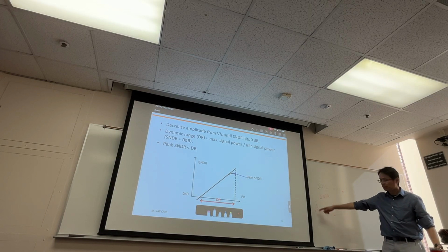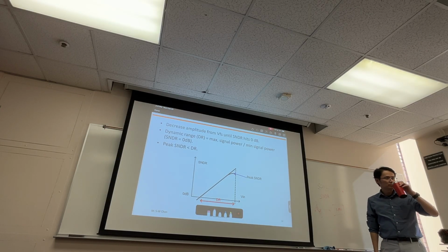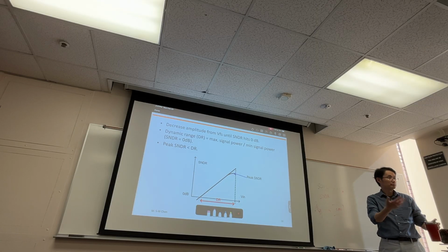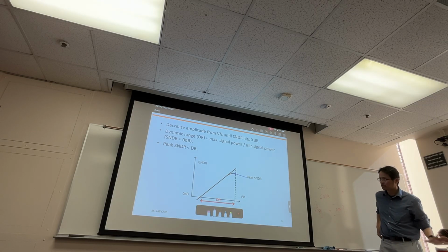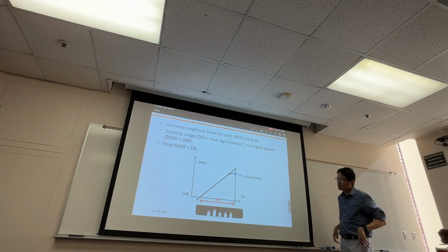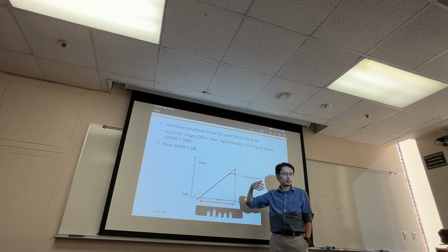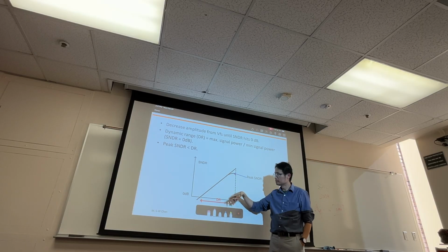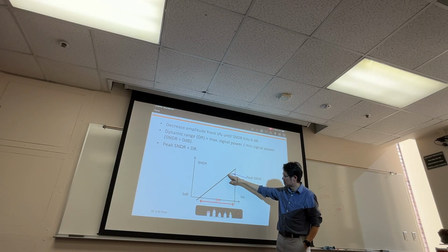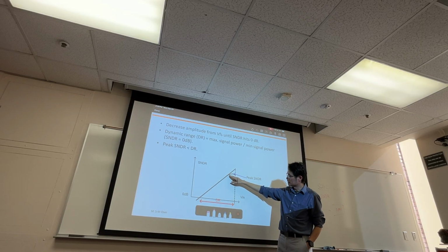So 2x input amplitude, 6 dB, right? Because in power it is 6 dB. Very good. So you should have this slope, right? Which means 20 dB per decade, right? Okay, so it will keep going up, and at some point, you see that it starts to plateau.